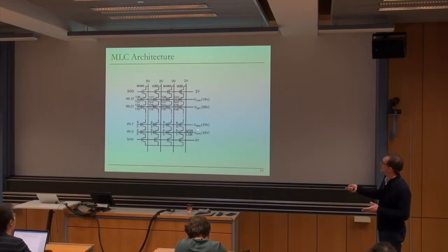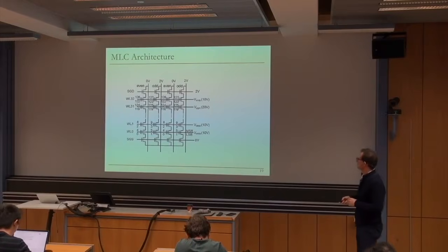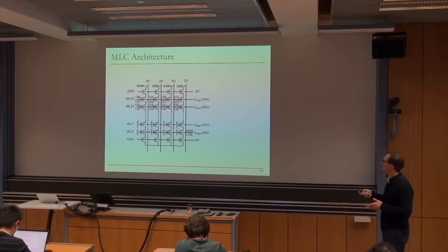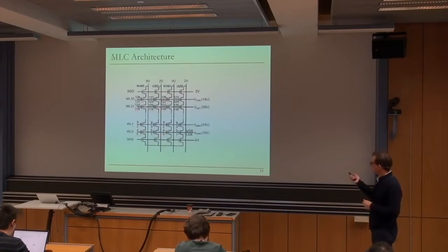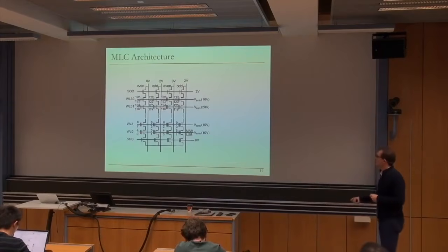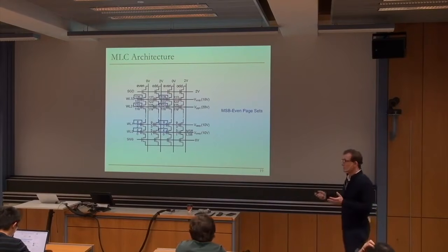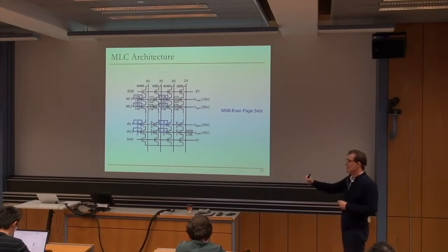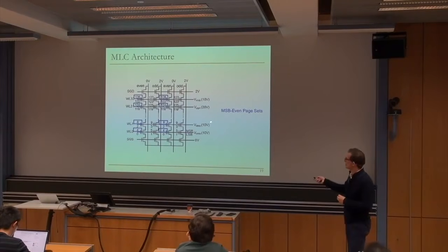You can see the MSB and LSB over here also. That's fine. But basically, if you see these figures, you should think about corresponding these to these states over here. One thing that I will talk about is that the order in which you program things matters. As I said, this is LSB odd page sets, MSB even page sets. The order in which you program things matters because whenever you program, you cause interference to the adjacent word lines because of these voltages that you apply.